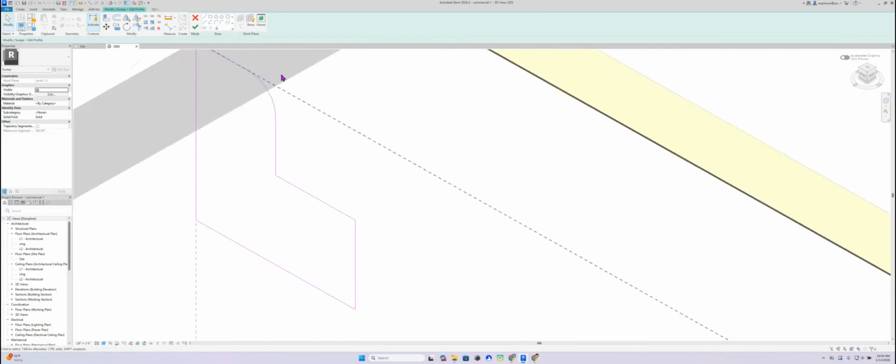I'm going to do the same thing again really quickly: another circle of 2 inches, and an endpoint arc here. So quadrant to quadrant, then move the cursor, and Revit will give you the perfect circle of 2 inches right there.